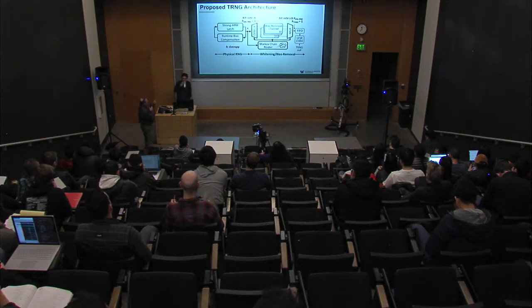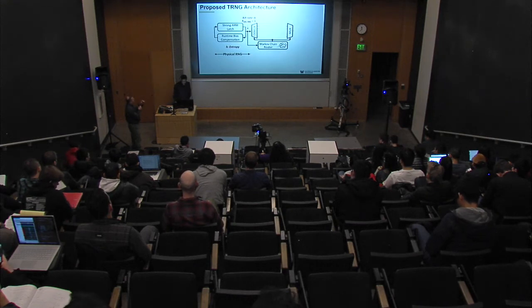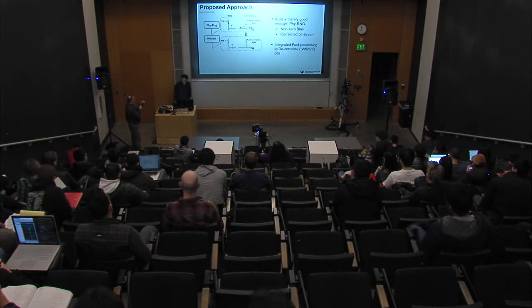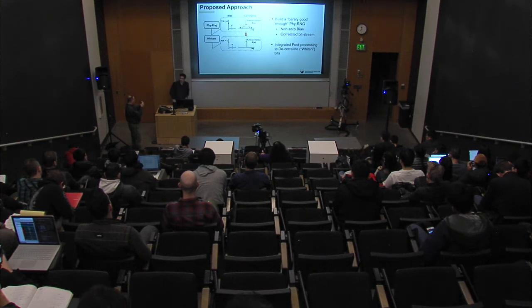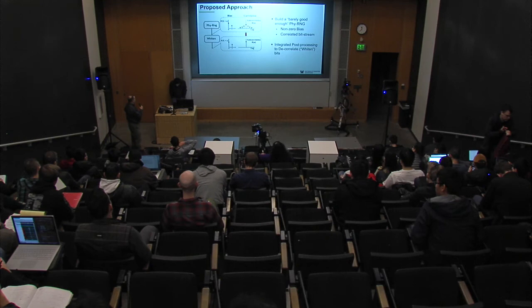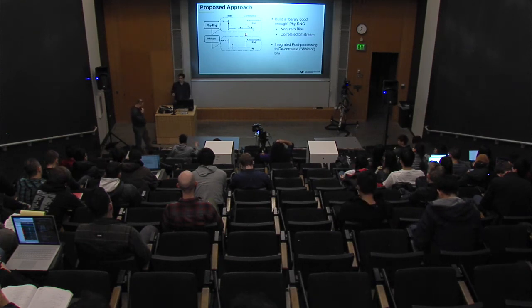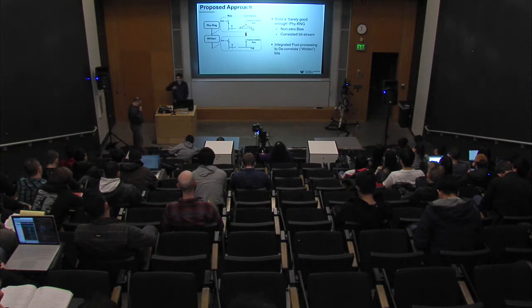This is going to be a dumb question, but in the comparator, could you address some of these issues if you had a pre-gain stage and coupled it? Basically you take the noise from the first stage and amplify it across a larger range, taking advantage of the full scale of the comparator itself. So I want to make sure I understand this. I think you're asking, can you have a wide-bandwidth preamp, maybe with a little more power, and pipeline the operation so that you hand it off to a second stage?